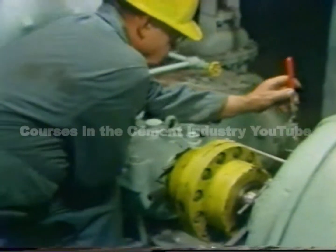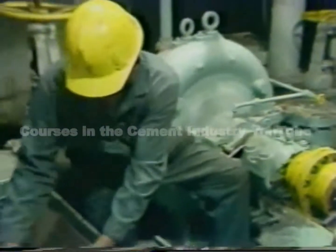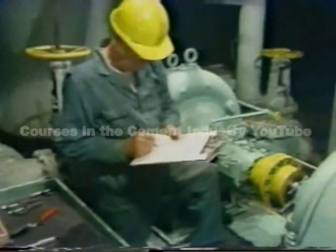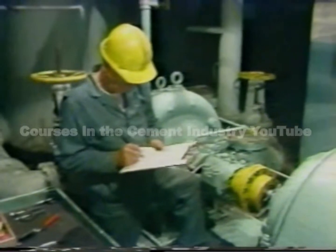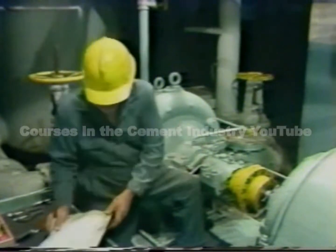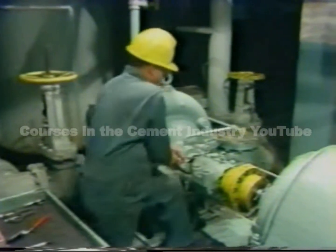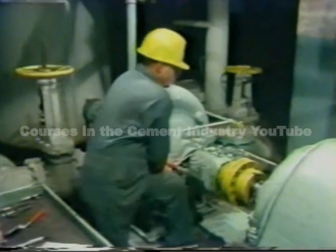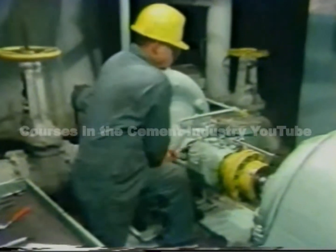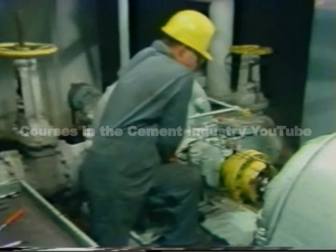He now has his final set of readings, and after they're recorded on the data sheet, he'll rotate the shaft back up to the starting position to make sure the dials come back to 0. If they do, he knows he has a valid set of readings, and they do. The next step is to analyze the readings.